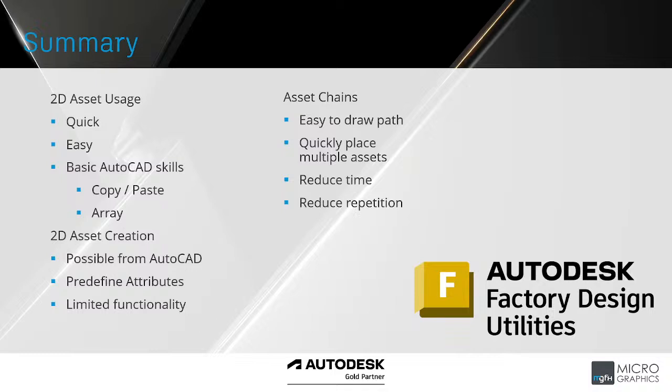From a 2D asset creation, it is possible from within AutoCAD. You can predefine attributes, but there is that limited functionality. One thing that you'll run into is connectors. You cannot define your connectors in the 2D side. So those connectors have to be defined in Inventor. Your landing surface defined in Inventor as well.